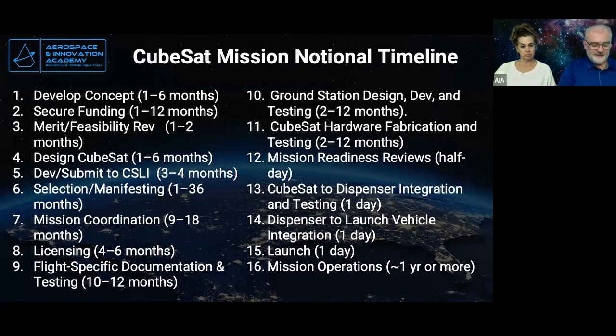But I was going to let you know there's a couple of options when it comes to your ground station. I chose to use a radio that talked above us. We were in an orbit below a network of satellites called Globalstar or Iridium. So I chose to use those because there were 24 Globalstar satellites. They were at 1,100 kilometers. We were at 550 kilometers. So our satellite could always see some of those satellites and talk to them.